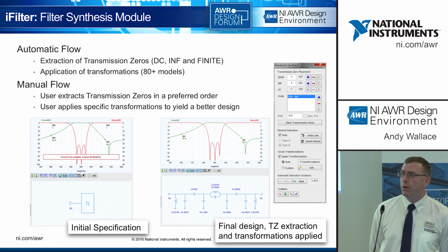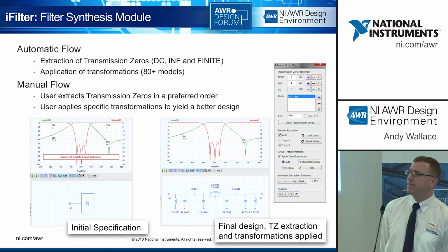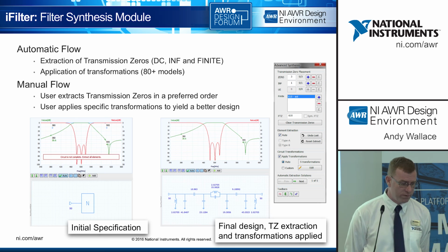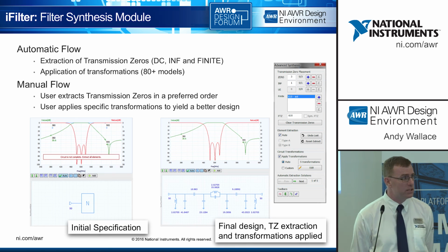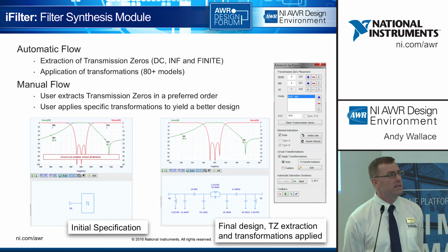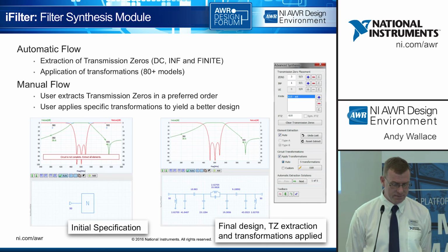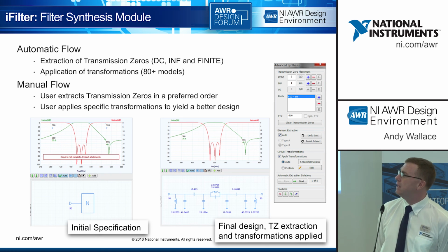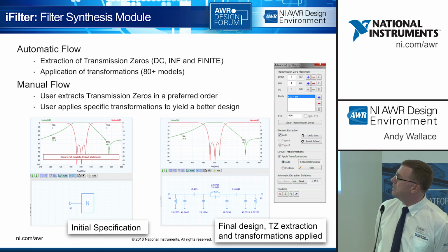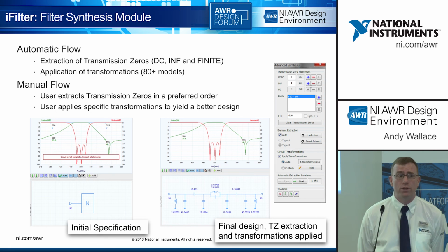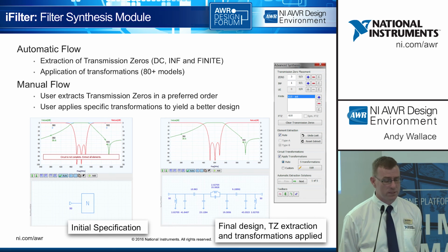The iFilter tool, we've improved that. I mentioned that we have the filter synthesis tool already in version 12. For version 13, we've added the ability to place zeros: DC, finite zeros, infinite zeros, and physically design the filter based on those locations. As you see from the screenshots, we can add those zeros, end up generating a circuit diagram, and that's exported directly into Microwave Office to build the filter.